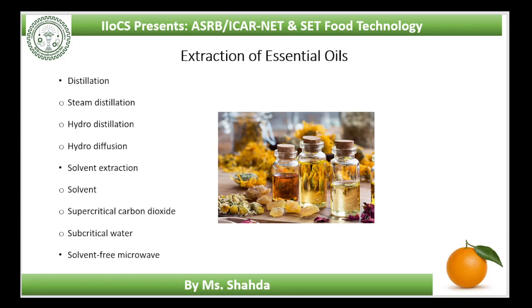Solvent-free microwave extraction has several advantages, involving higher yield and selectivity, shorter time and being environment friendly. This is a combination of microwave heating and dry distillation performed at atmospheric pressure without any solvent or water. Isolation and concentration of volatile compounds are performed in a single stage.